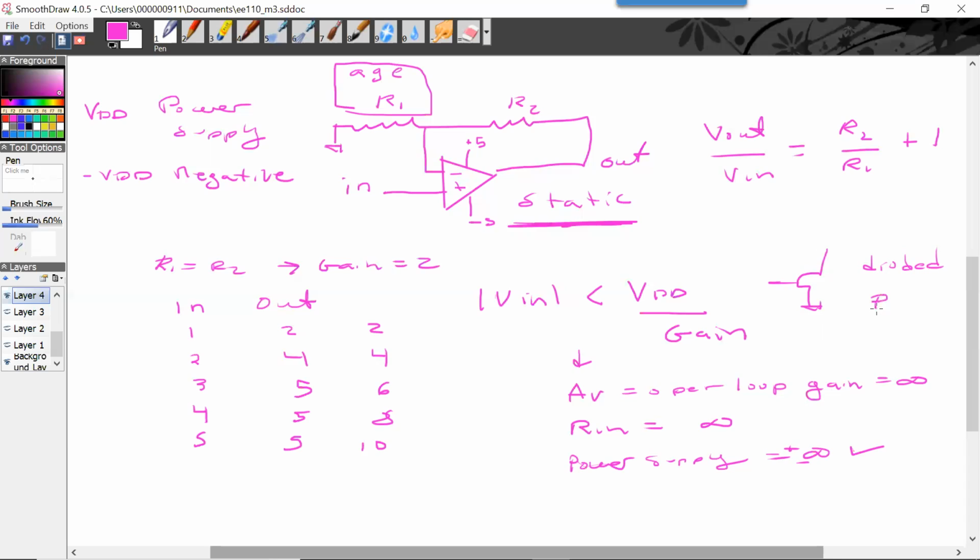Diodes have regions of holes and regions of electrons that are separated by a depletion region. And so if you have two kinds of charge separated by a dielectric, you have a capacitor. So every diode has some capacitance. So therefore every transistor has capacitance, and there's ones that I haven't mentioned. That means if an op amp is made out of at a minimum of six transistors, there are existing capacitors. And these capacitors will make your op amp not work.